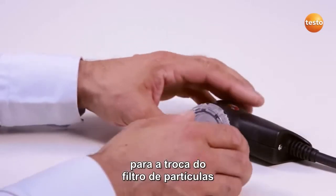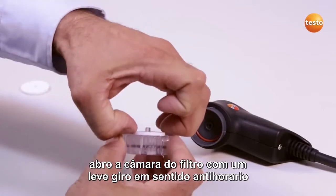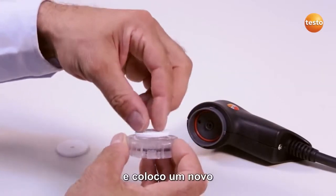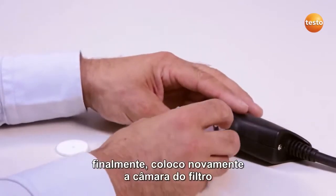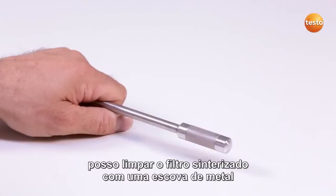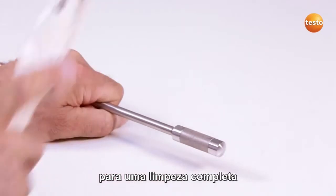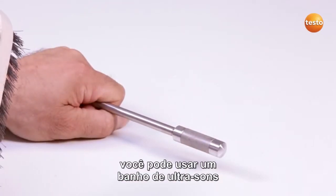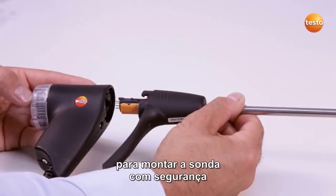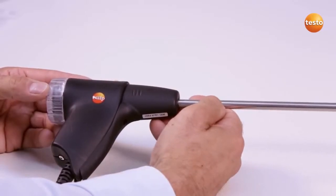In order to exchange the particle filter, I open the filter chamber by turning slightly anti-clockwise. I remove the filter disc and replace it with a new one. I finally replace the filter chamber and close it. I can clean the sinter filter with a wire brush. To clean completely, I can use an ultrasound bath or denture cleaners. To reassemble the probe securely, the probe shaft must fully engage onto the probe handle.